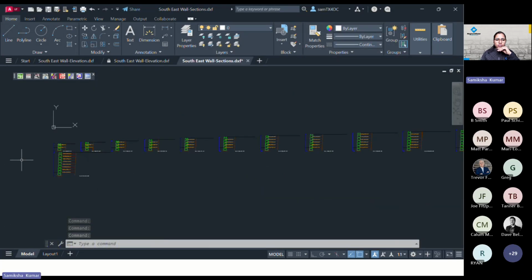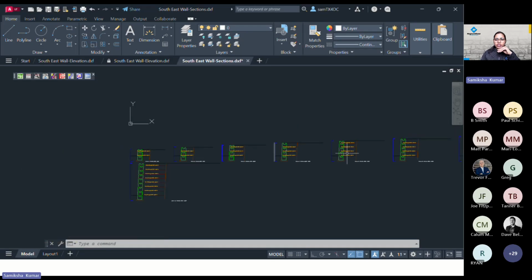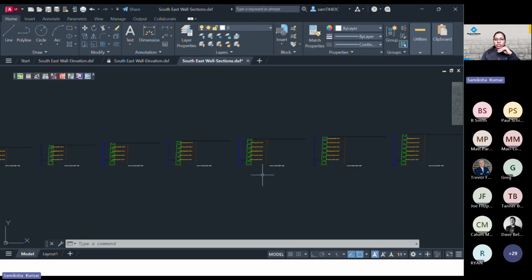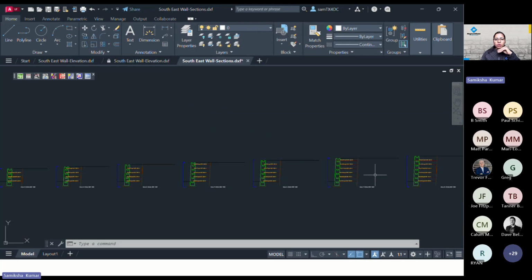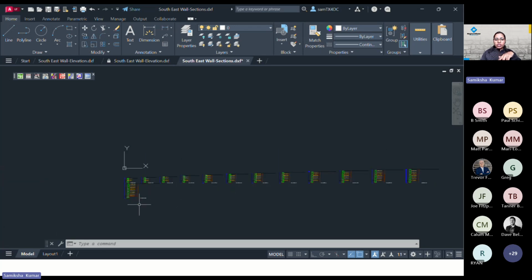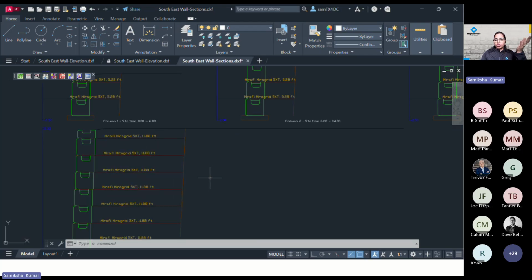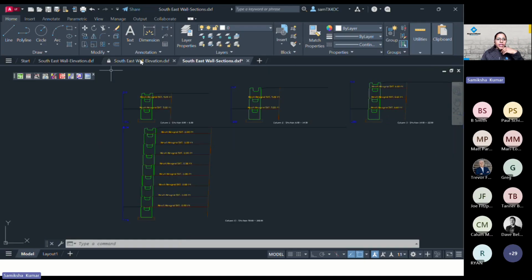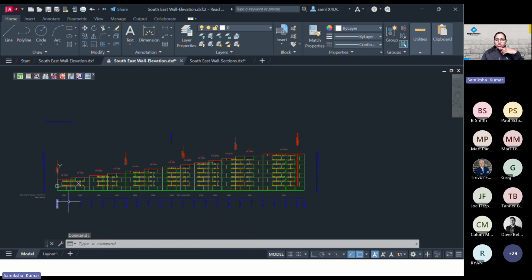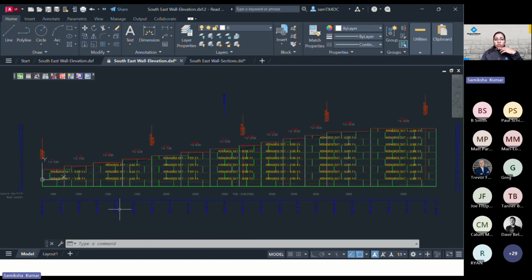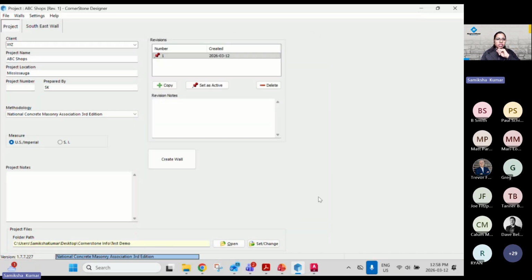So these are the sections. It took every panel section from our wall design and gave me a wall section here. Now, for my package, I could use the maximum height to give the engineer an idea of the maximum geogrid length that I'm using and what kind of geogrid I am using. Then I have the elevation view. This is the elevation of our wall, and you can make edits as per your template if you have one. We take this and paste it into our template and make edits accordingly. So yeah, this is how you get the AutoCAD export from the CTI software.